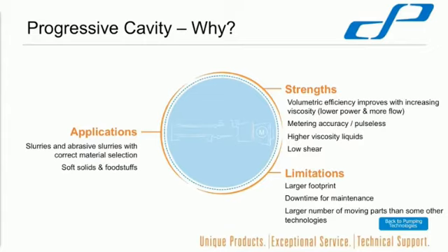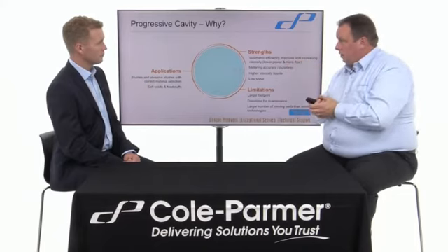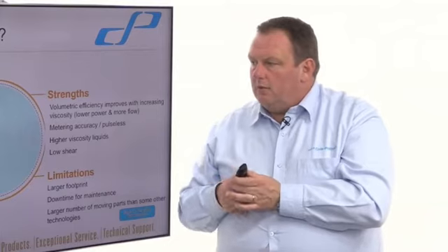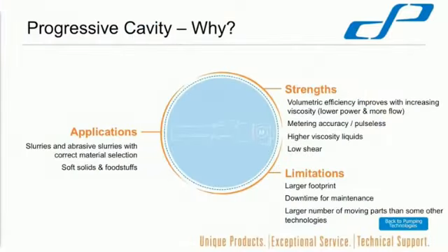So again, a lot of pharmaceutical products can go through this sort of pump because it's not pulsed and because it's delicate, and this will treat them delicately. Their biggest core things are the clay slurries for all the chinaware and things, and all the hand basins and all the toilets. And then from light fittings, there's a lot of chinaware in light fittings and things like that. So they do all of that. And they can handle soft solids and foodstuffs. So they can push things without damage.